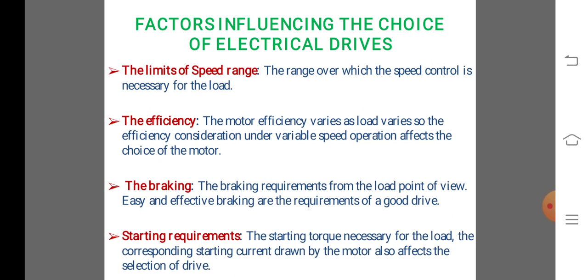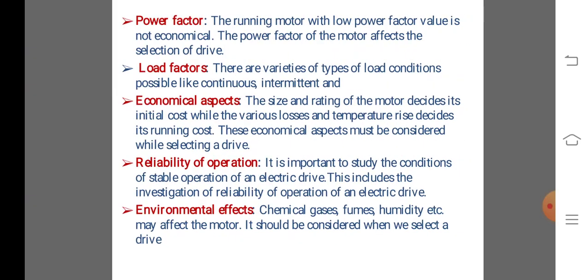Starting requirement always considers the starting torque necessary for the load. The corresponding starting current drawn by the motor also affects the selection of the drive.